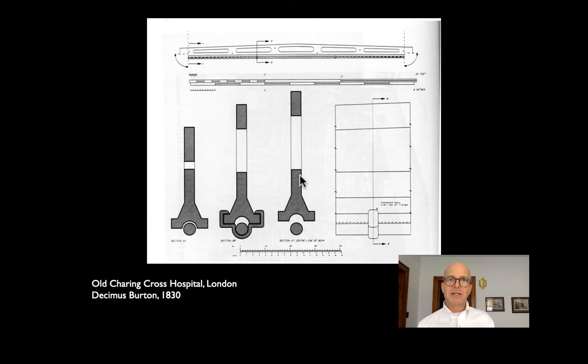So you can see that they've got a kind of good moment diagram shape, a good longitudinal shape. And then interestingly enough, they make the bottom out of a rod of wrought iron, which is much stronger in tension than cast iron. So they knew that there was compression at the top, tension at the bottom, just like in any beam we would design today.